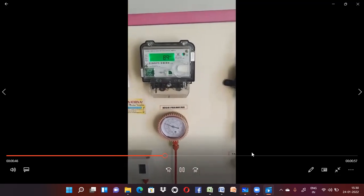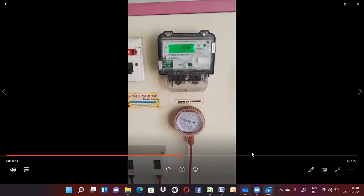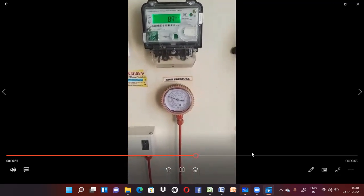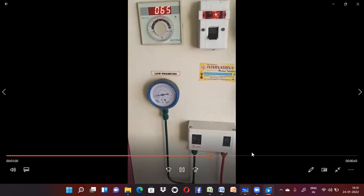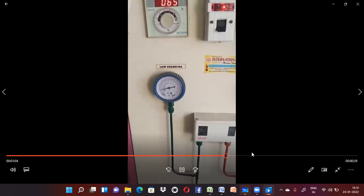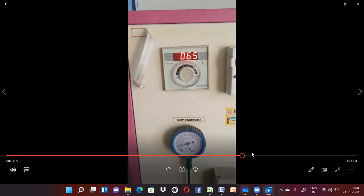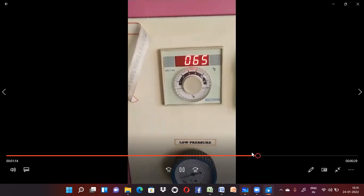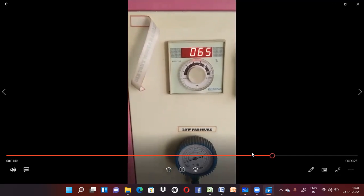This is a digital meter used for registering the power input, and the high pressure of the system is being registered here, shown by the red line, and the low pressure of the system is being shown in this pressure gauge, given by the green line. This is the thermometer, where we can show T1 to T6 temperatures, which are fixed at different points of the system.